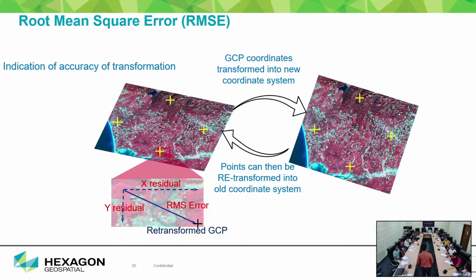Suppose you have satellite data of 1 meter, 2.5 meter. If you go for the least 4, then you have a spatial resolution of 4.8 meter. So this shifting should not be greater than half of 4.8, which means 2.4 meters. It should be minimized as much as possible below 2.4 meter. So guys, you got my point?